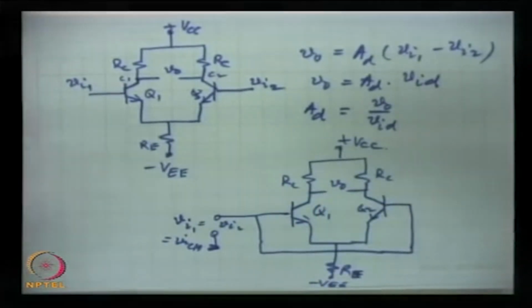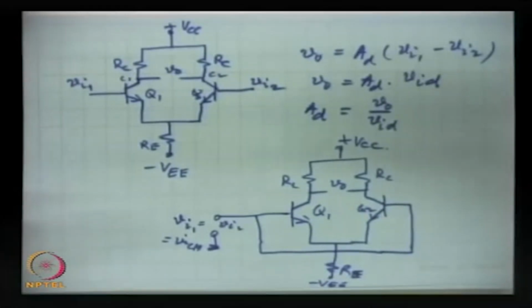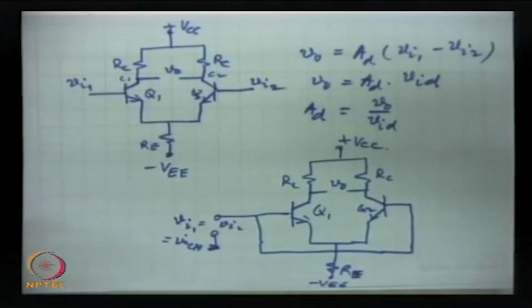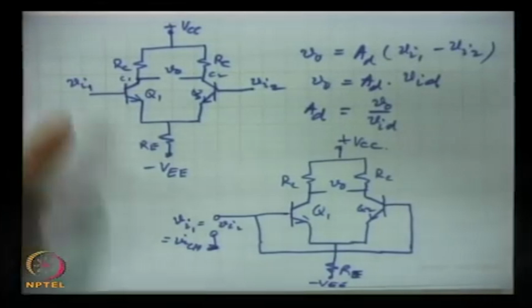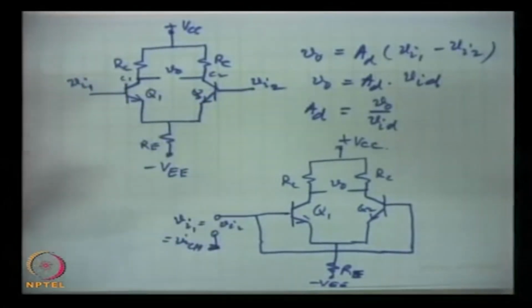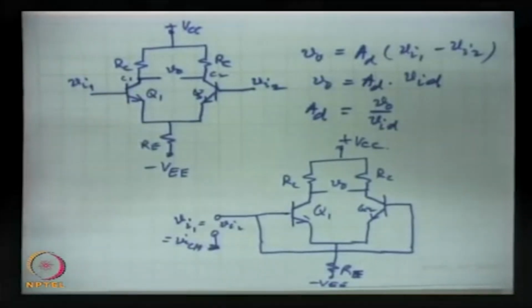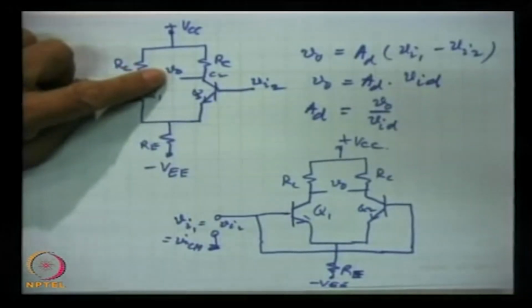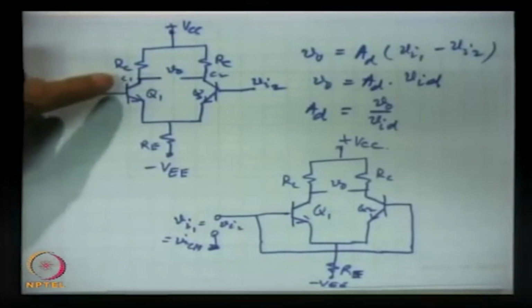These are direct coupled amplifiers and hence they will respond even to DC. So, we can use DC voltages, two DC voltages in the first case differing slightly, we measure that difference and we measure the output from the two collectors.